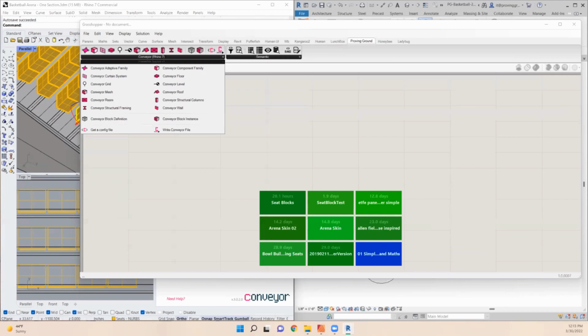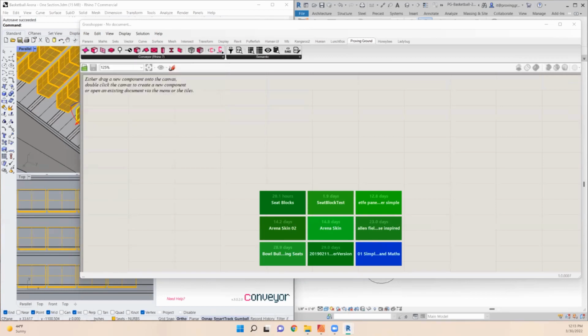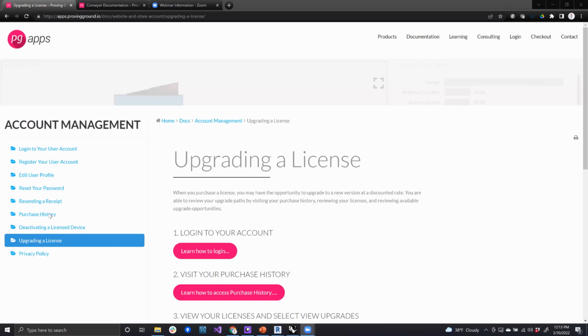Esther's asking, how do we modify a floor from Rhino into Revit? So I think we had touched on it earlier, but if it's a more simple floor, just a flat floor with a boundary curve definition, then you can modify that once it's been imported. But if it's a more complex floor, then you can modify it in Rhino and then bring it back.